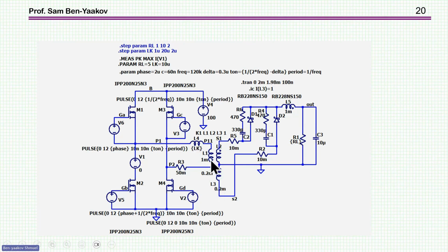Many times it'll be a sort of integrated magnetics, in which the coupling coefficient is smaller than 1. So within the unit itself, there is a leakage, but I've again put it outside so we can see what is really going on here and what the voltage is here. We'll talk about it in a minute. Then I have two diodes, and I've put a snubber to damp some oscillation due to the capacitance of this diode and the secondary. And here is the filter. This is like a regular full bridge PWM converter.